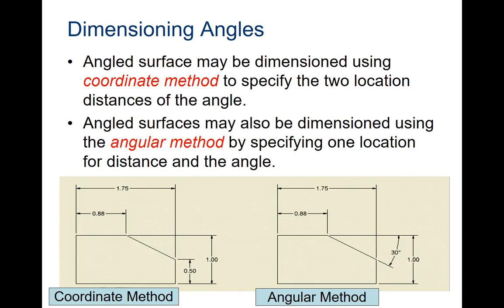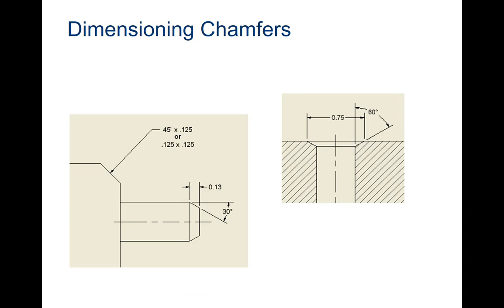All right, now we're going to talk about dimensioning chamfers. Again, there's a couple of ways to do this. You can use the angle method that we just talked about, or you can have Inventor tell you the degree. So 45 degrees times what the length is, and then you can just plug that into the chamfer feature. If when you're dimensioning you just hover over the chamfer, the mouse will change to, I believe, a little circle, and you drag away and you'll get your chamfer dimension.